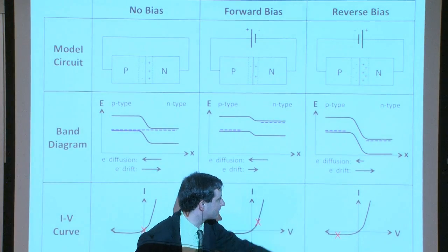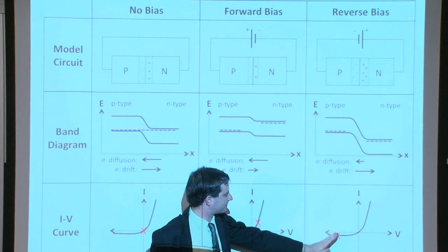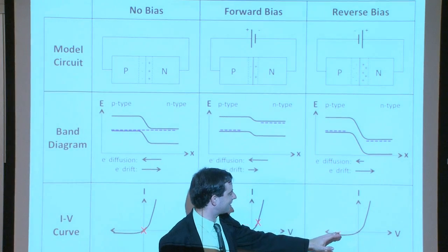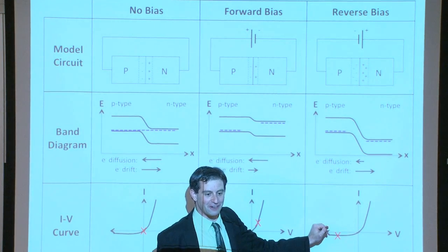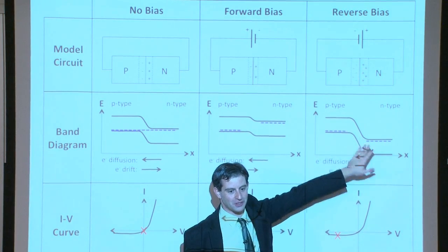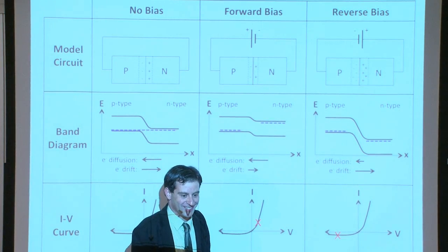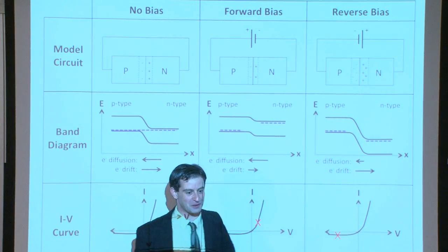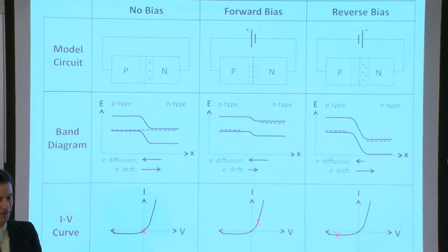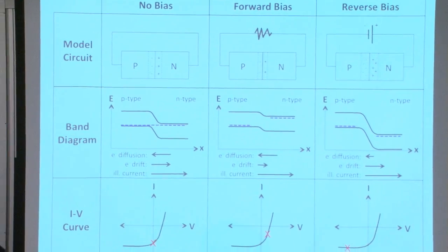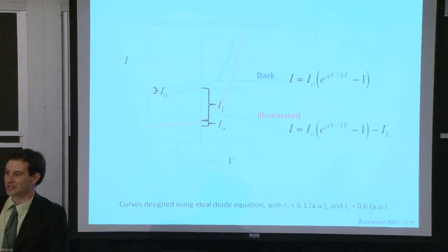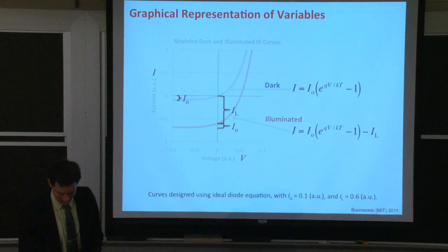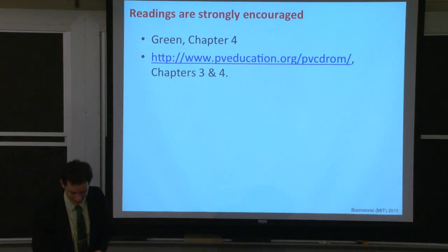So if the solar cell is reverse biased, and the reverse bias current at reverse bias voltage is not low enough, in other words, if the pn-junction is not strong enough, you could have a catastrophic failure of your module by just shading one of your cells. Thankfully, this is one of the tests that are done with the solar simulator to prevent that failure mode. All right, I'll entertain deeper dives with questions. I'll try to keep the lecture focused on the broader general topics, but if somebody is interested in learning more, I'm happy to dive in.